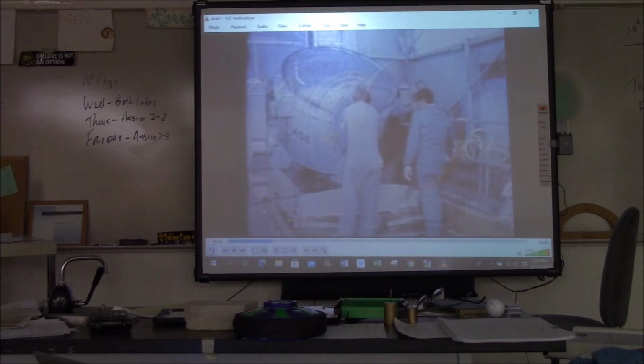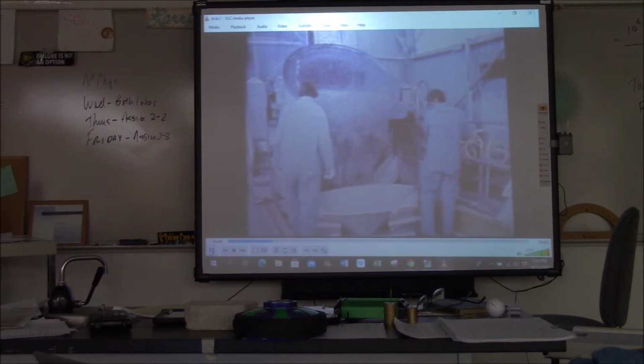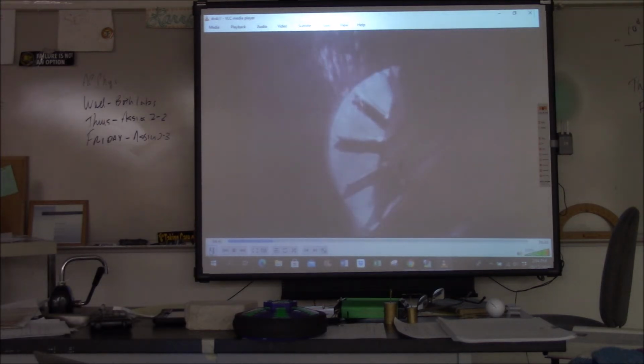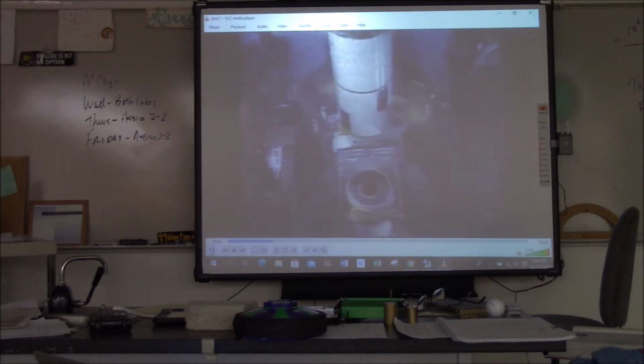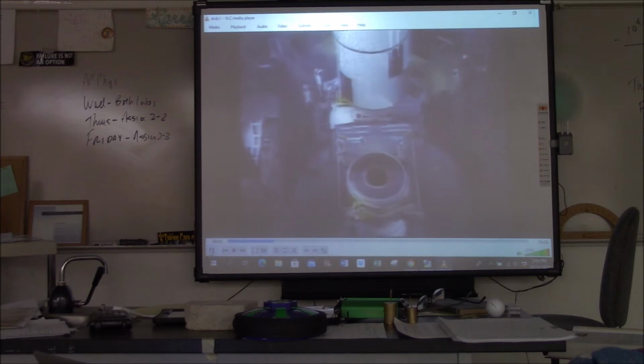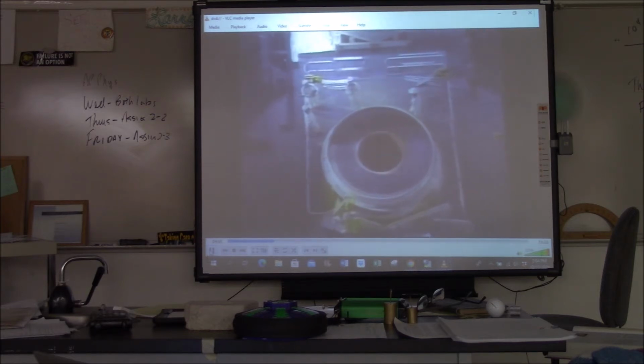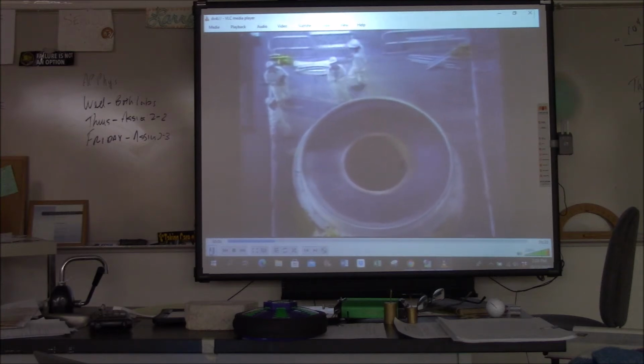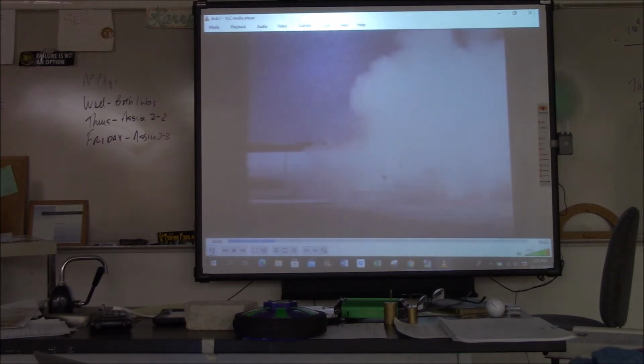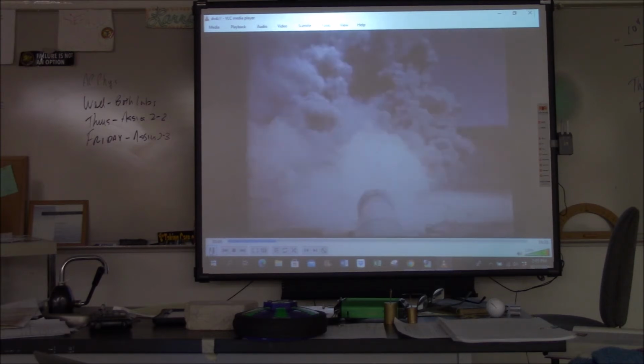Solid rocket boosters use a propellant which consists of aluminum powder as the fuel and ammonium perchlorate as the oxidizer. A rubber-based polymer binder is also added. This mixture fills the entire length of the solid rocket motor, except for a hollow channel extending through its center, which serves as a combustion chamber. When ignited, the propellant burns from the center out towards the sides of the casing at a nearly constant rate. An extraordinary amount of thrust is created.